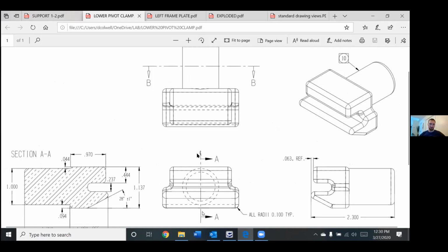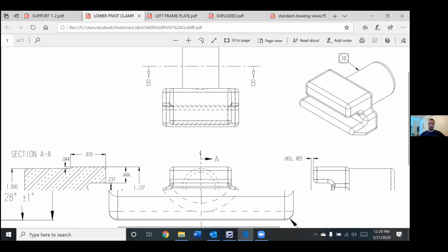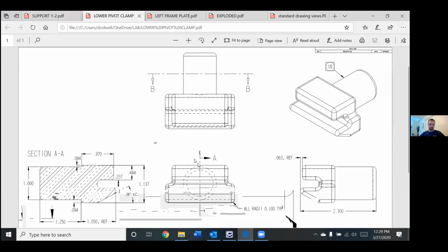If you put a center line right through the middle of a hole, then that hole has to lie in the center of the part. And so it locks down a lot of things, and actually can save you from having to do as much detailing. So that center line is where we pulled this section view from, and it allows us to talk about the diameter of the shaft.